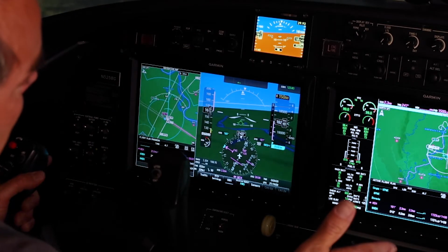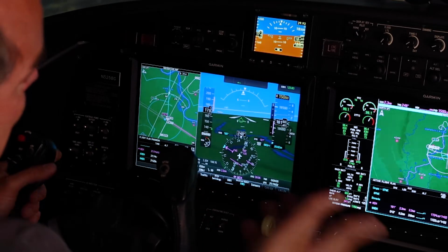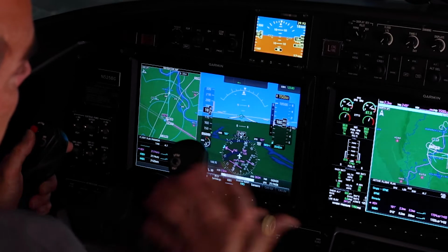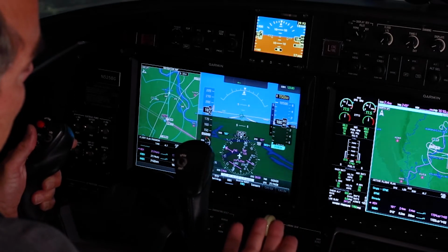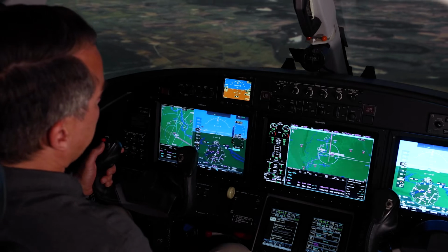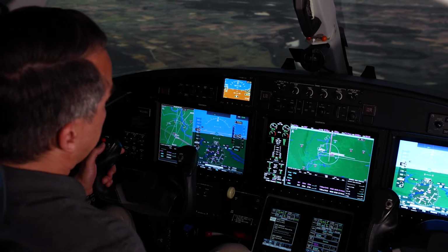When you're unloading the airplane, you're in a less than 1G situation. In that case, your stall speed is going to go down. If you suddenly load the airplane up as you recover to wings level and straight and level, you could find yourself encountering a stall. So be aware of where your airspeed is during the recovery.